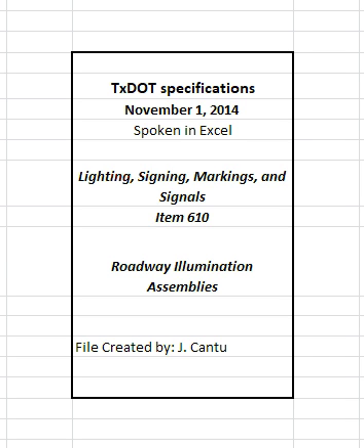Prevent scarring or marring of the poles, luminaire arms, and luminaires. Replace damaged components. Repair damaged galvanizing in accordance with section 445.3.5, repairs. Repair damaged painted areas of a roadway illumination assembly in accordance with item 441, steel structures or item 445, galvanizing. Stake, install, and align each roadway illumination assembly as shown on the plans. The engineer may shift an assembly's location, if necessary, to secure a more desirable location or avoid conflict with utilities.